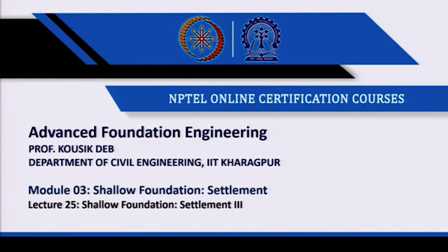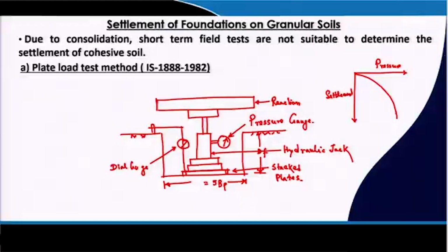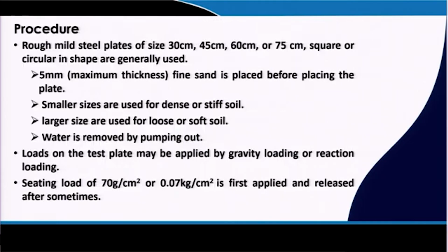So, last class I was discussing the plate load test. I have discussed that ultimately we will apply pressure and measure the settlement, and we will get the pressure versus settlement curve, and that curve will be used to calculate the bearing capacity or the settlement of the foundation. So, I was discussing the procedure: we have to apply 5 millimeter fine sand before we